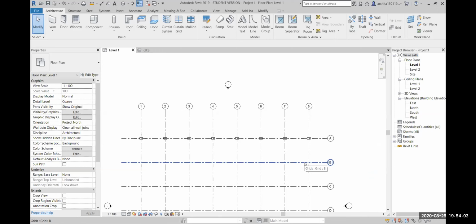Mainly even in working drawing, the first grid line which you have to put is for the basement or for the column layout. And then throughout in every plan, you will be having the same grid line. The grid line doesn't change with your plans, because even if there's a grid line running in between the wall, that means the wall is a load bearing wall. That will be same throughout the level. It's not a non load bearing wall which can change.